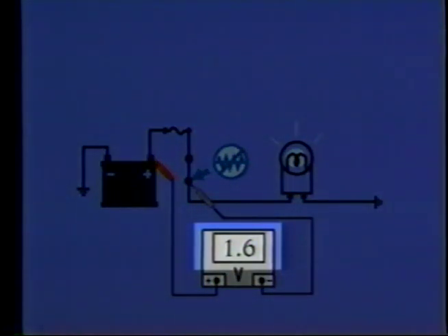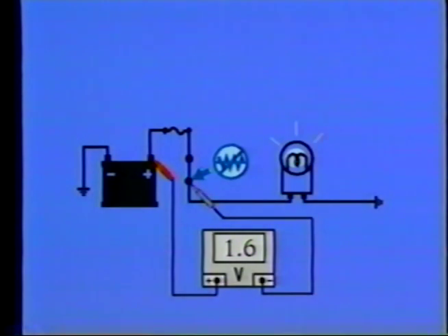If the voltmeter indicates greater voltage loss, there's high resistance in the circuit that needs to be isolated and corrected. To isolate the resistance, perform voltage drops between closer points in the feed path until the voltage drop-off point is isolated. One area that technicians overlook is the ground circuit, which can also be an area of unwanted resistance.